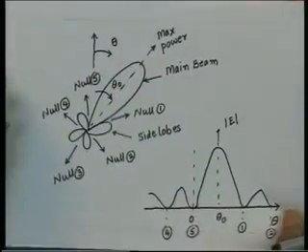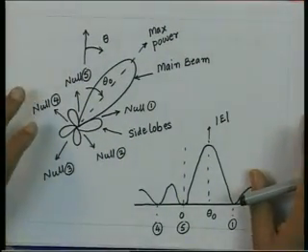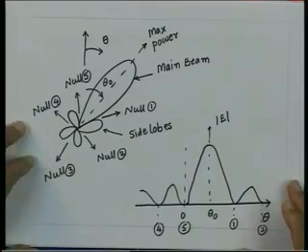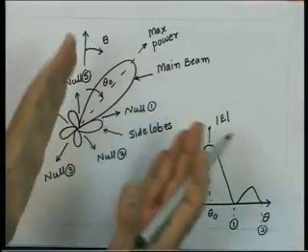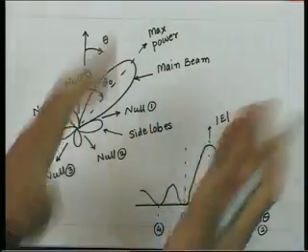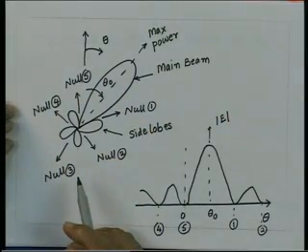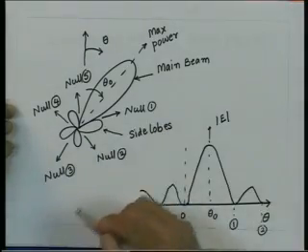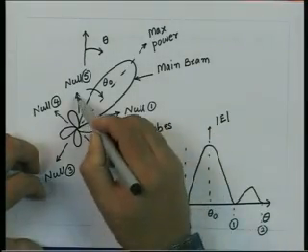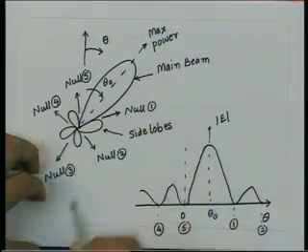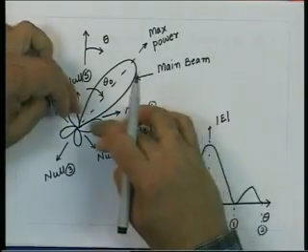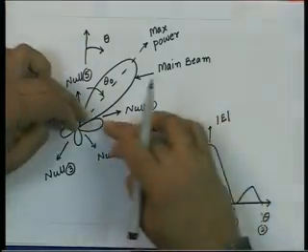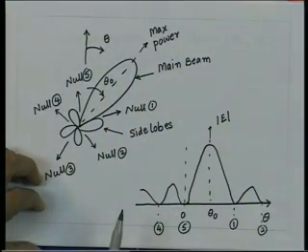The second thing you can see from this radiation pattern is the angular sector over which effectively the beam is illuminating the region. There are various possibilities. One is, if I go to the nulls, the radiation goes to 0. So, I have an angular sector decided by these 2 nulls over which the power goes in the main beam.